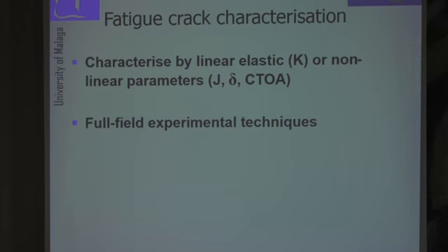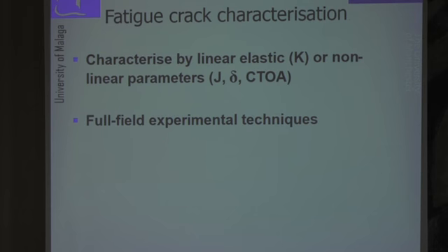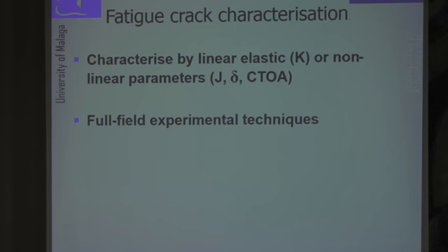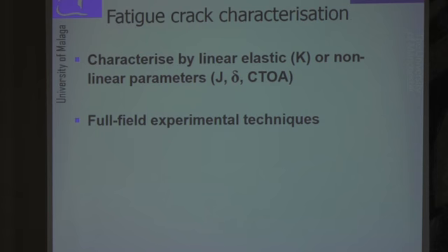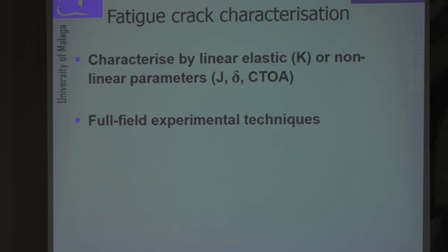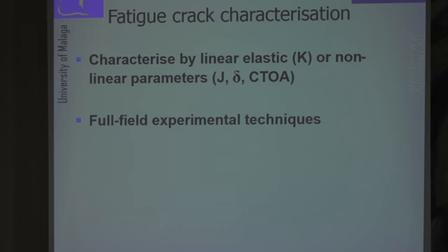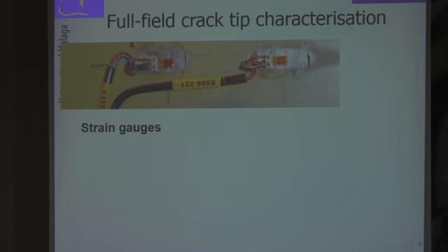So the aim of this work has been to characterize crack tip fields for fatigue, and this can be done by linear elastic means through the stress intensity factor, or non-linear parameters like the J integral, crack tip opening displacement or crack tip opening angle. We've seen today and yesterday a few examples of such type of characterization with full field techniques. The initial work was done with strain gauging, and then with the development